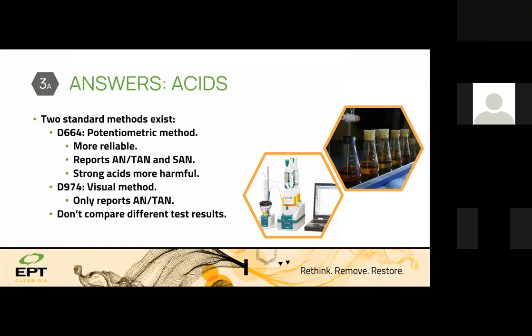The color change plays a role here. I don't know if you have done it; I have done it with my own hands in the labs. When you do it, it is based on a human, a lab technician, to report the acid number. He adds some liquid to the oil, and based on the color change, he reports the acid number. So there can be mistakes in this test.